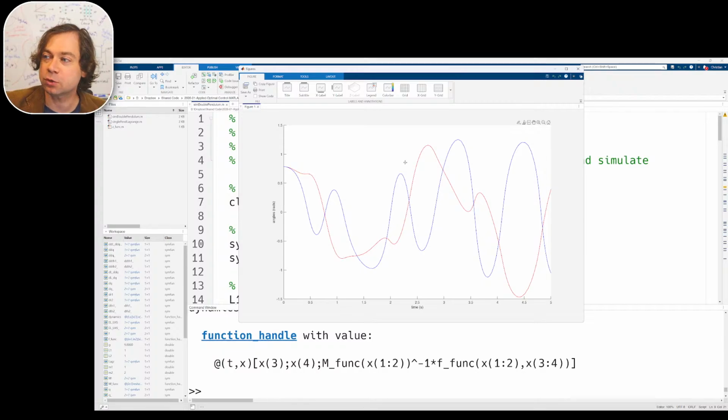Now, you're kind of trusting me that I did a good job, and in fact, it looks like the real pendulum dynamics. One thing that we learn in mechanical engineering is to check if it's working well. It's good to show an animation of it. It's a fantastic check. There are other things you can do to make sure that your system is working correctly. A great one is if you have an energetically conservative system, like we do, we could check to make sure that energy is in fact conserved. We could add up all the kinetic energies and the potential energies, and it should be constant. We don't have any friction or anything in this model of a double pendulum. We can check it. It works.